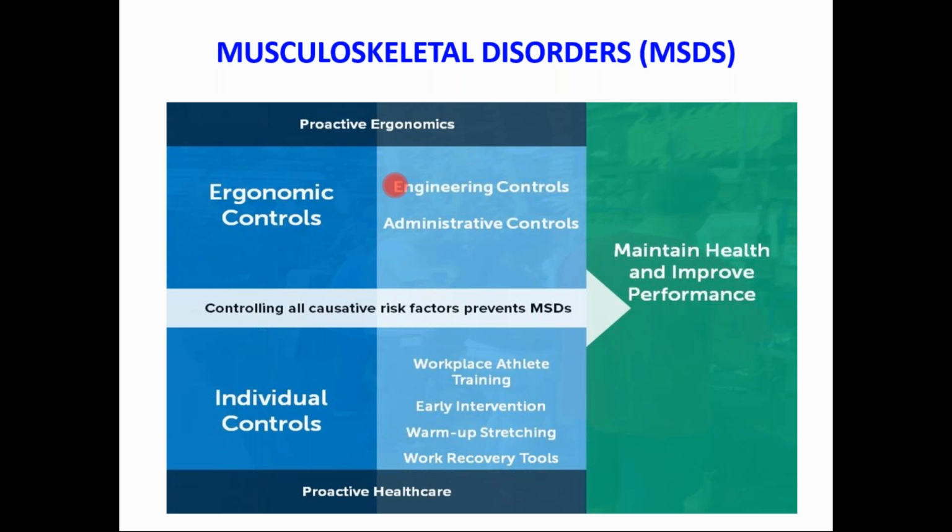control. If sometimes the SOPs are good, but the workers are not going to follow these SOPs, or workers are not going to follow the proper gesture and posture, then we have to supervise these activities, we have to observe these activities, and then we have to guide that particular person that you should go this way only. So this is nothing but administrative control. So depending on the condition, depending on the activities, we have to go for engineering or administrative controls.